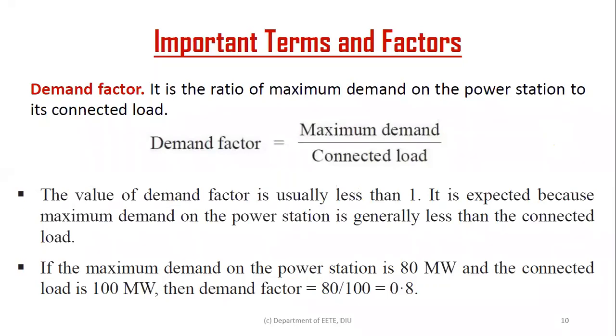So what is demand factor? Demand factor is a ratio. That ratio is the maximum demand divided by connected load. So what does it mean? Suppose in my home I have 5 lights and 2 fans, but I will not use all the things at the same time.